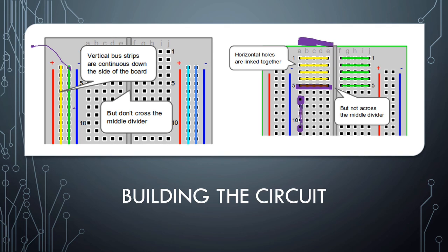And then if I needed to connect it to an LED, get rid of this one, my LED, one leg would need to be in the same row to be properly connected. So it can be any of these. It doesn't matter because they're all connected, remember. Oops, I keep trying to grab my eraser here.